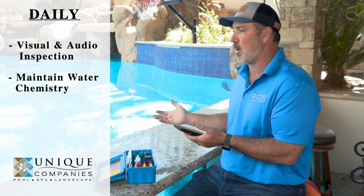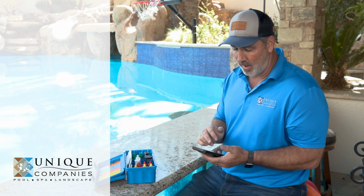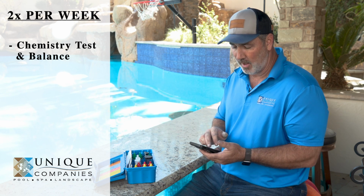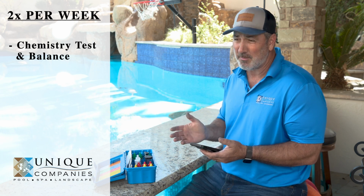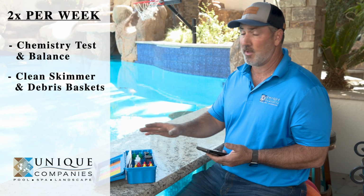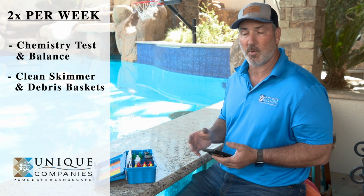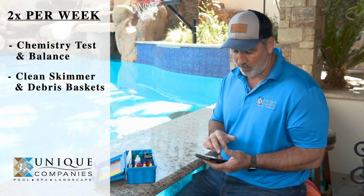And of course, I say maintain proper water chemistry because we want the water chemistry maintained throughout the week. Twice per week we have in our proper maintenance, chemistry testing and balancing as required. So before I said a couple times a week, twice per week if you can get out and check your water chemistry and make proper adjustments, sometimes maybe more in the summertime, okay? Twice per week, clean the skimmer baskets and your debris baskets. We talked about that a little bit in the orientation. The skimmer baskets, debris baskets, once or twice a week, depending on the time of year. You don't want those to back up because it restricts flow at that point.